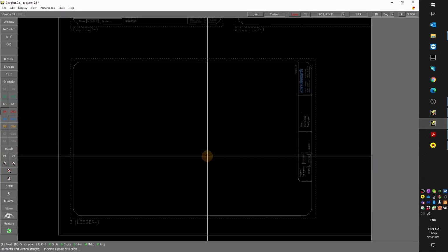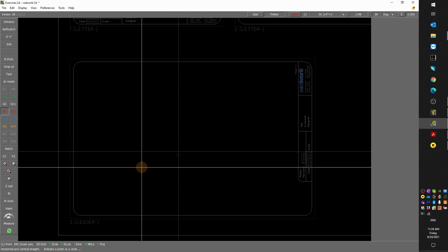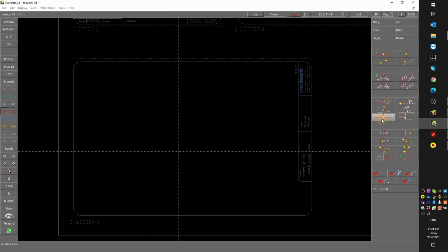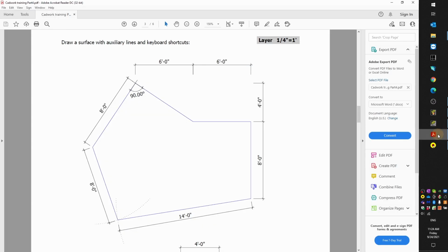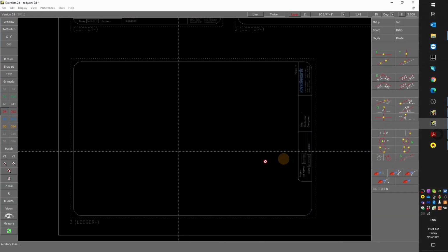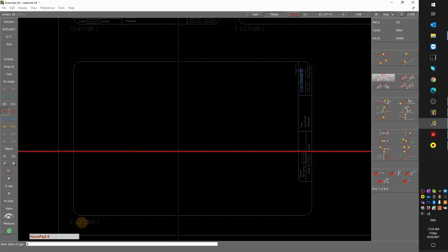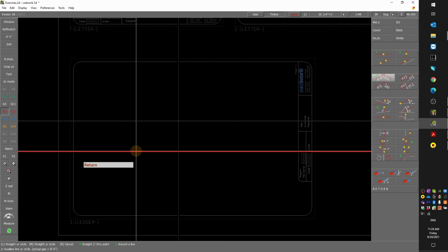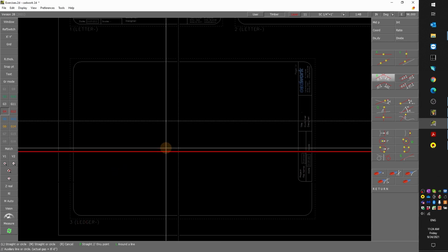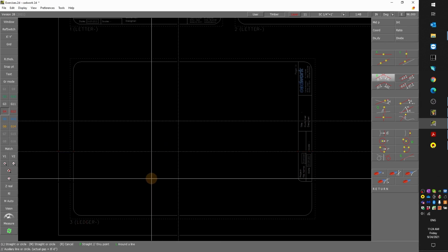I'm gonna start here. So I added like a cross, and then I said 8, and then perpendicular. So offset 8 feet. So remember to press the foot mark, and then I'm gonna go 8 feet here.